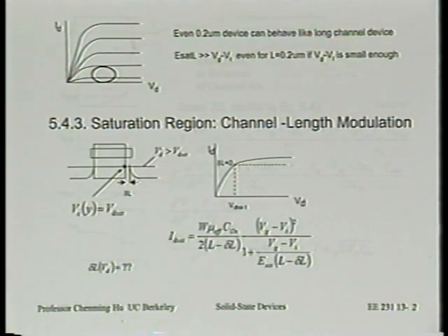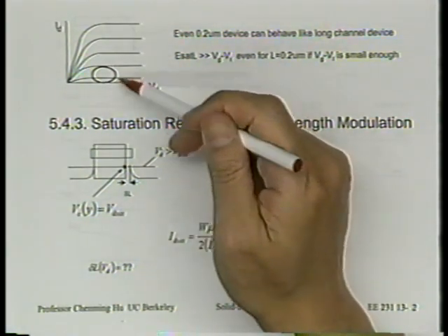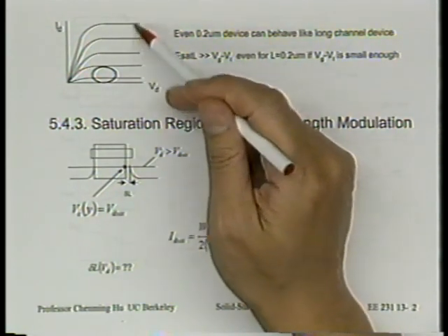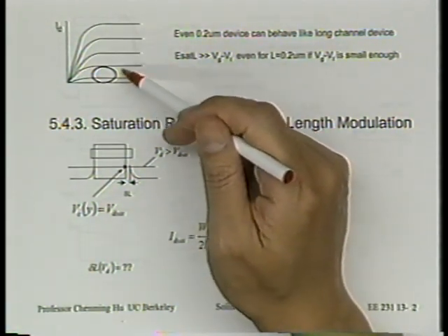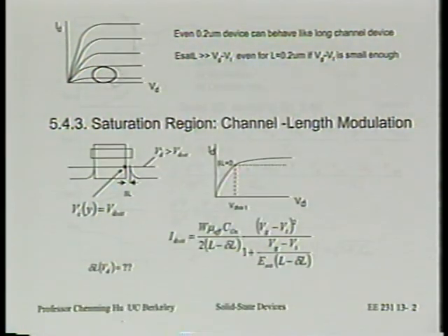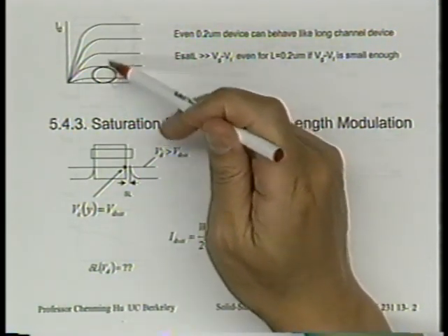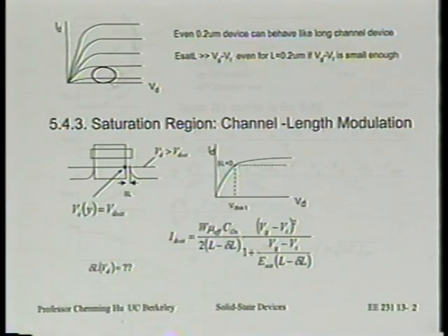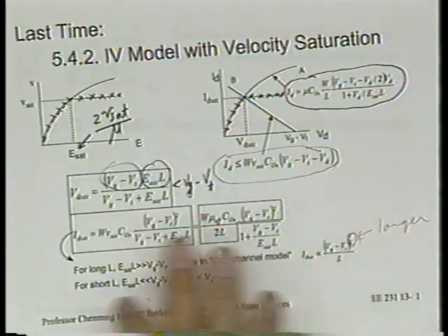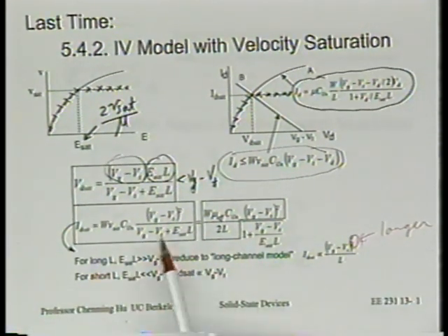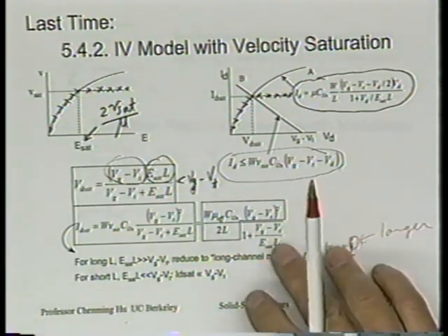But for most of the transistors here, you do see Vg minus Vt to the first power. So you cannot say they are long channel transistors. And yet, when you look at here, it reverts back to the long channel transistor behavior again. Okay? And for analog designers, this can be really a benefit. For digital circuit designers, where this region is important, it's certainly much better to think that ID is proportional to Vg minus Vt to the first power. And the equation that we derived last time covers both regions smoothly. You don't have to make an assumption. They actually go from one extreme to the other smoothly. All right? Okay. Any questions?